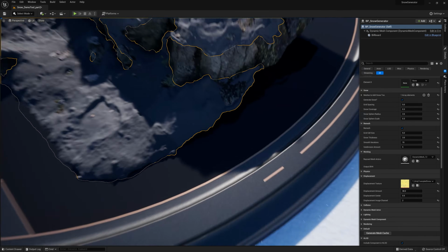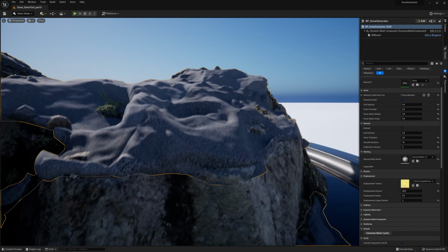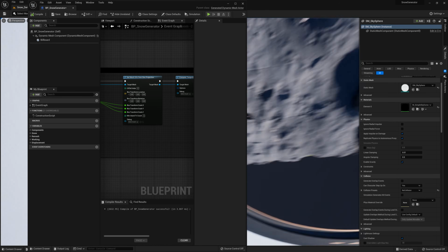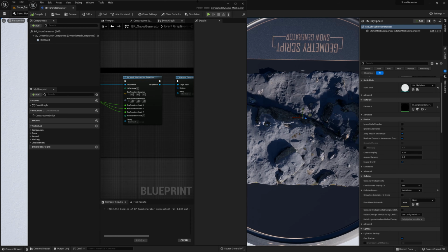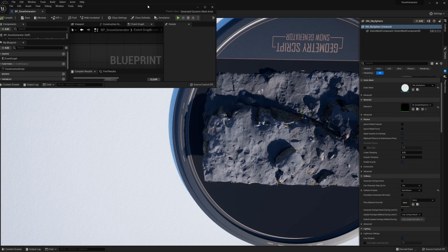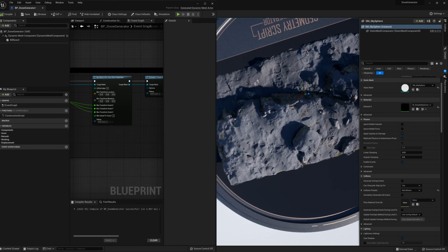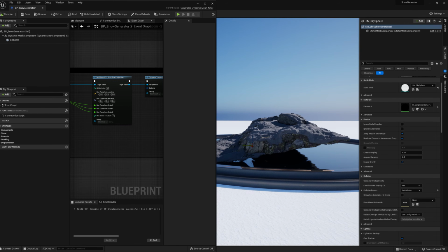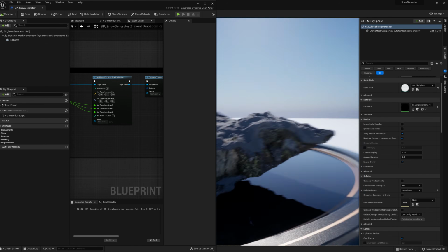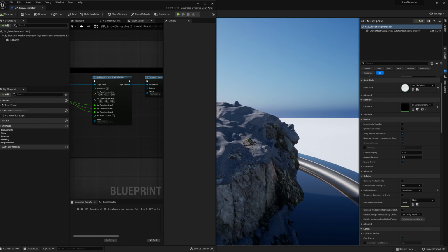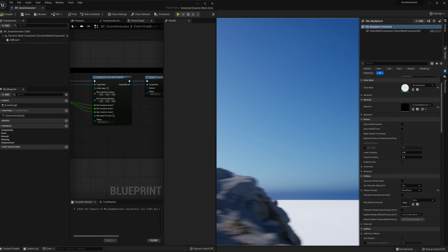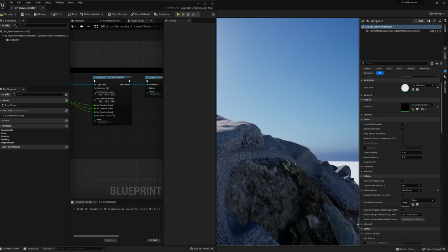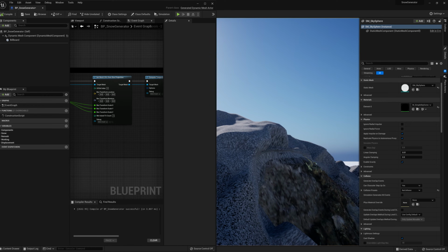One thing I do want to talk about a little while we're on this subject is we're using a box projection, which basically means that it takes all the faces which point upwards like this and creates UVs for those, creates all the faces that point sideways on and creates UVs for those. Same for the front, the back, etc. But what that can mean is that you get bits where it's pushing up, but bits where it's kind of pushing out.